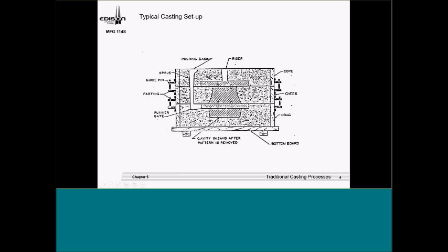As we're looking at this PowerPoint, I also try to stress that when we put this flask together, we want to make sure we've got the guide pins and that we have it marked for proper alignment, so that when we take this apart to pull the pattern out and then button it back up, putting in a runner and so on, we have it aligned. Because if we don't, we could be 180 degrees off, and next thing you've got a mismatched casting.